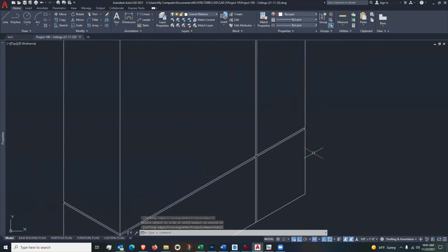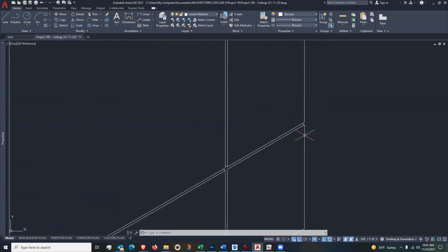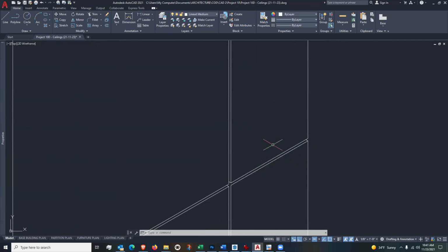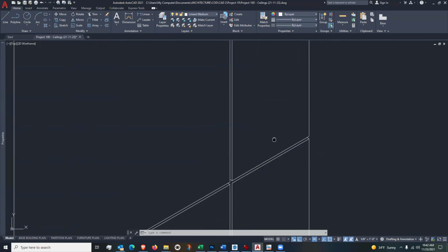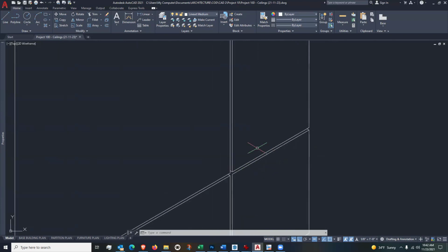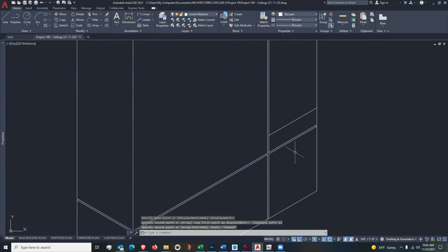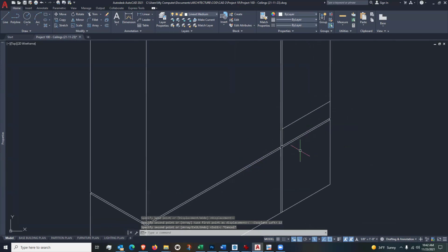here. All right. And actually, now this reveal is not just a reveal, it is a panel, and it comes up a foot. So I kind of drew this needlessly, it looks like. So let me copy this up a foot. Oop, I can't copy it up a foot. So let me change my isoplane and then go. Now I can go up 12 inches.